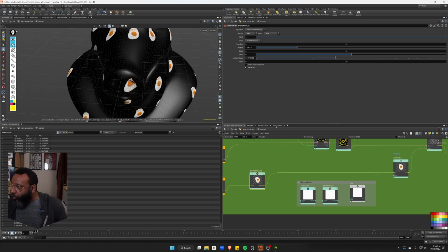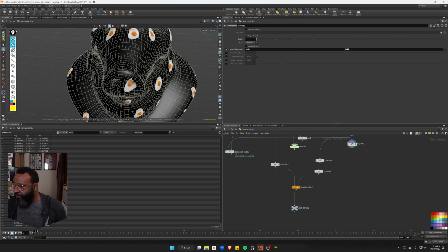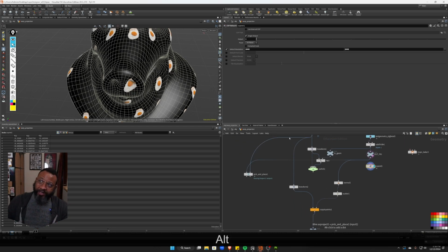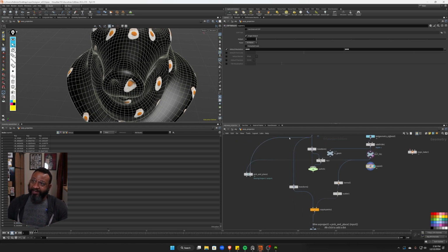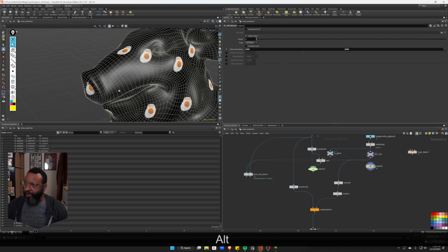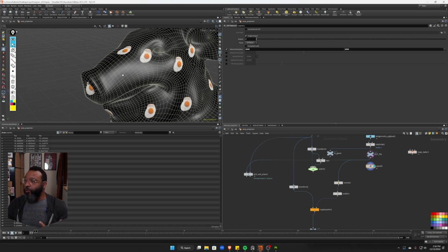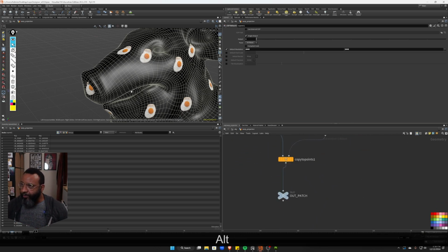And once again, the only thing this system really cares about is the patches. You can generate those patches however you see fit. You could draw your geometry on here, and as long as that geometry has UV values, that will... what's the word I'm looking for, transfer over. So the possibilities are endless. You could use the trace node, you could use the poly draw with some of the UV tools, and it's just this giant open playground where if you know just a few tricks, you can do a lot of damage. So yeah. I think I'm gonna leave this here.